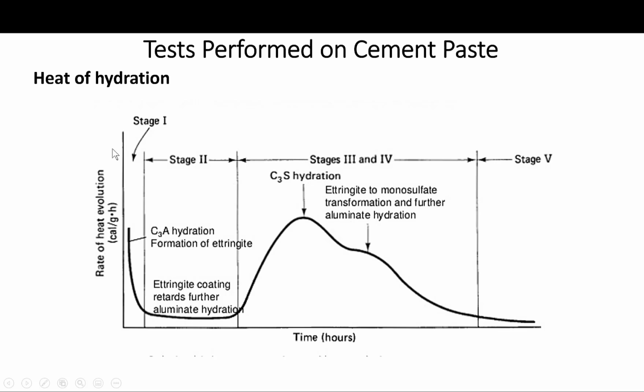We can use it also for measuring hydration at different temperatures, because we can control the temperature. Quantifying retardation and acceleration, the influence of any additions or additives we add to the cement, proportioning of the cement-based products, the hydration mechanism of pure compounds. If you want to study the hydration of C3A, C3S, or whatever, again, this is a great tool. Again, we will talk about this curve in later lectures, so don't worry about it for now.